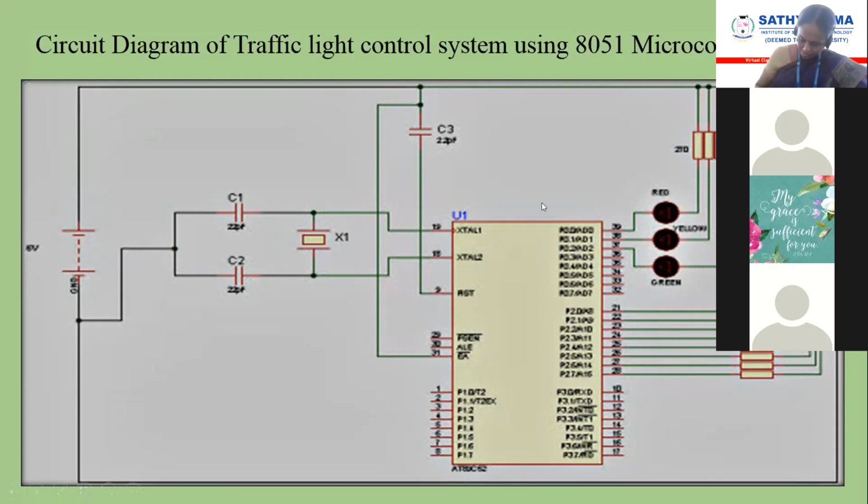The display unit consists of 3 colors of LEDs, red, yellow, and green, with 12 LEDs of 3 colors each. The detector unit is used to detect the presence of vehicles in front of the IR sensor and photodiode sensor. The control unit detects the presence of the vehicles in front of it, and also calculates the traffic density.